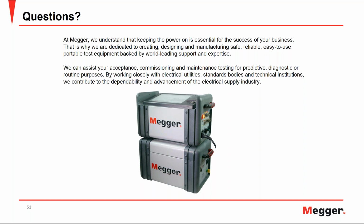So this one is a little bit difficult to find out, because whenever you're going to have a high power factor value, basically it is pointing towards higher losses, and higher losses mean higher leakage current.